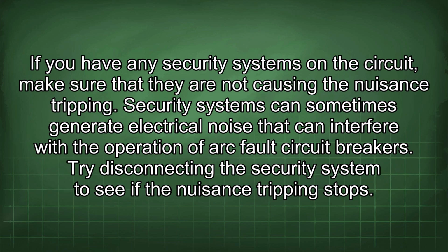If you have any security systems in the circuit, make sure that they are not causing the nuisance tripping. Security systems can sometimes generate electrical noise that can interfere with the operation of arc fault circuit breakers. Try disconnecting the security system to see if the nuisance tripping stops.